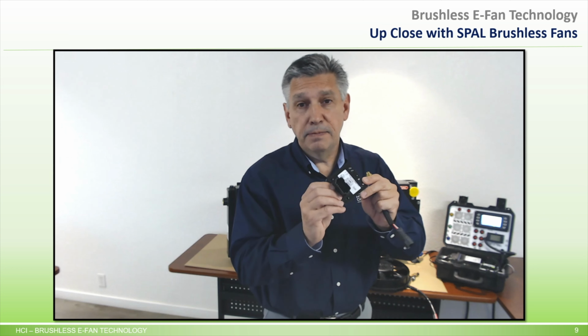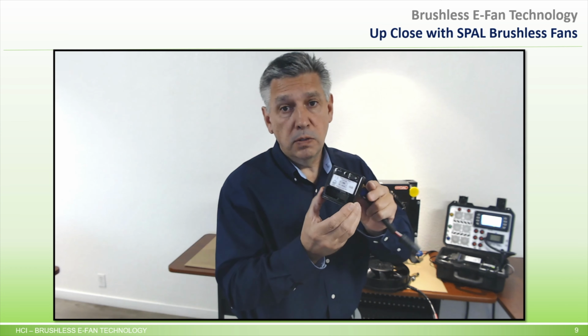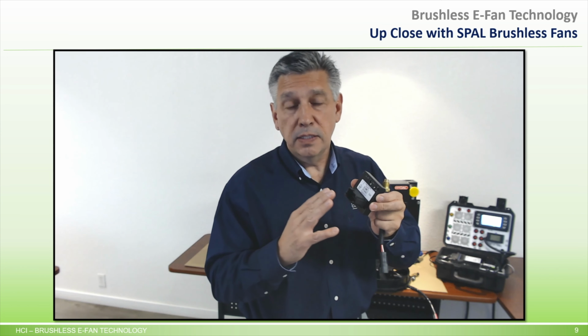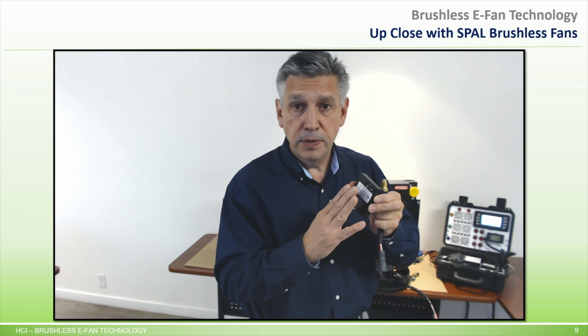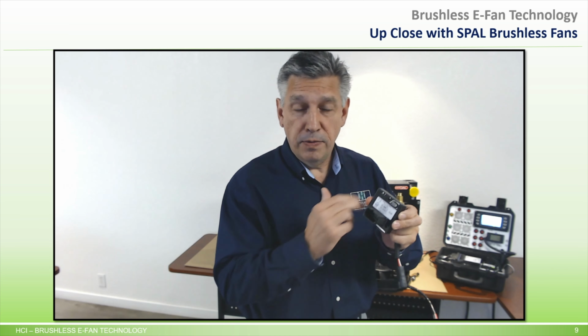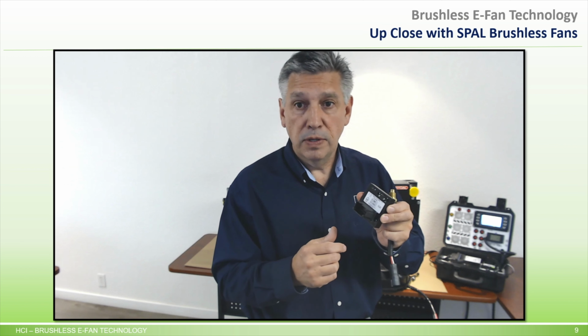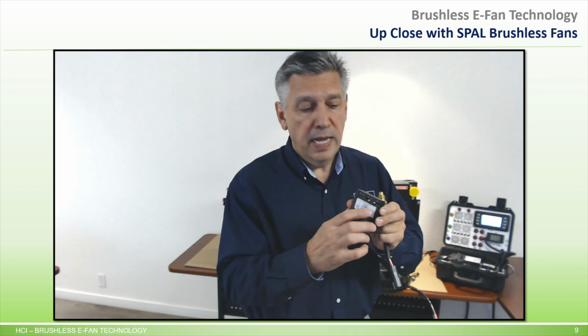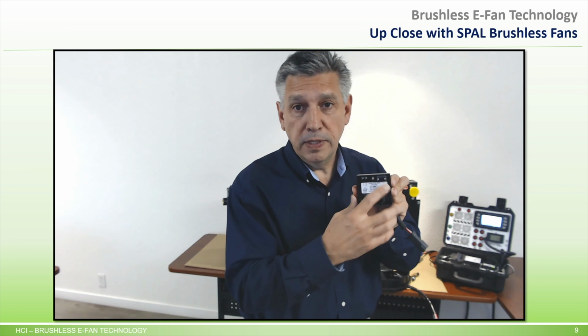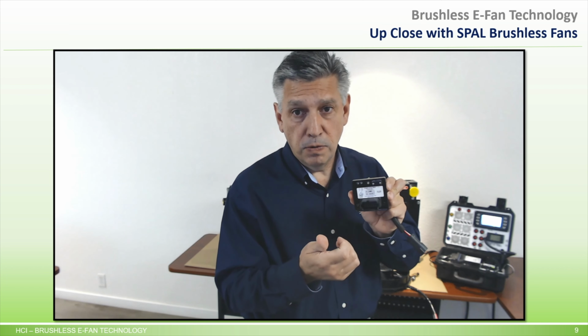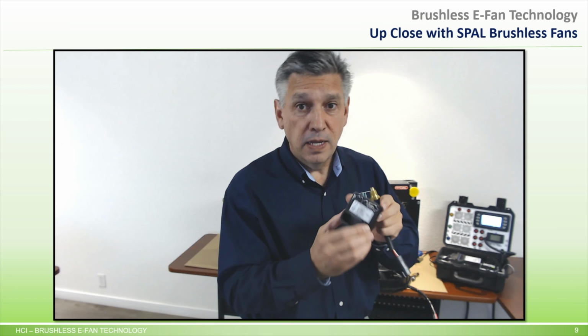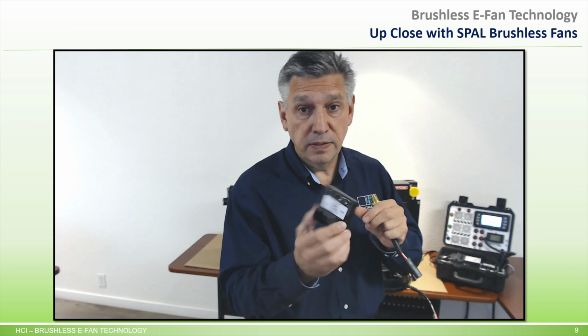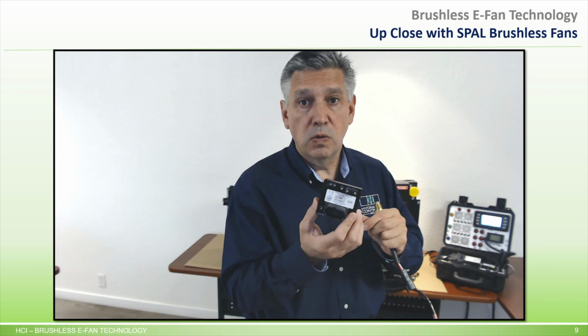So here we have an EMC controller. This controller can tie into your CAN bus, can tie into sensor inputs, 0 to 5 volt, the thermistors, which I'll show you in a minute. It has a mini USB port that you can easily plug in to program and configure it. You don't need to be a programmer to configure this thing. So just an easy controller to get set up.